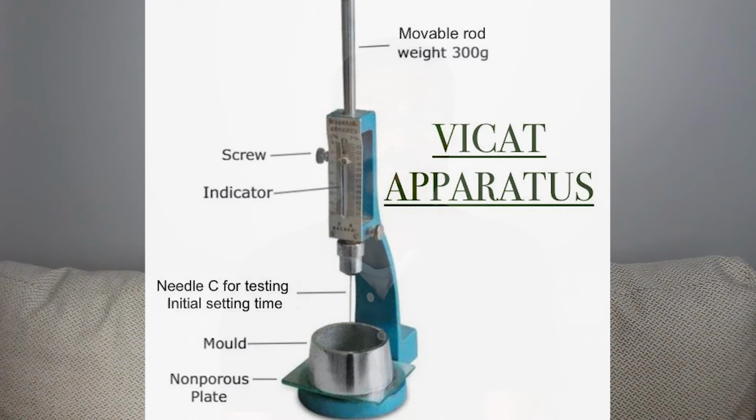Setting material is indented by a needle of 1 millimeter diameter under a load of 300 grams. The setting time in this test is defined rather arbitrarily as the time when the needle is no longer able to penetrate to a depth of 2 millimeters into the material. The setting time measured using this method is normally less than 30 minutes. However, a longer time is required before the material has matured sufficiently to allow any further work to be performed on the cast without damaging the surface.